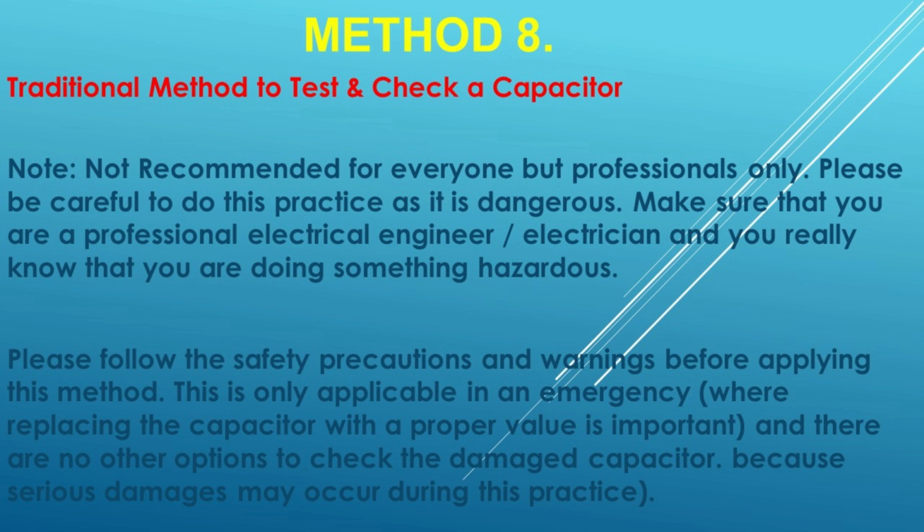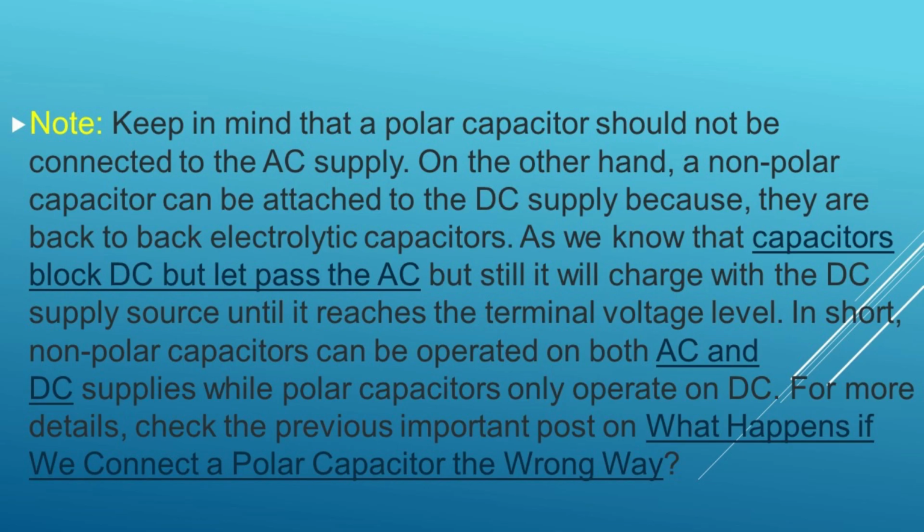In case of absence of DC source, like batteries, the high-rated capacitors, i.e. fan capacitors rated for 3.5 F, 120, 230 or 400 V, you may use 120-230 VAC, but you have to connect a series of resistors, say 1K ohms to 10K ohms, 50 watts, to connect between capacitor and 230 VAC supply. This way, it will reduce the charging and discharging current.